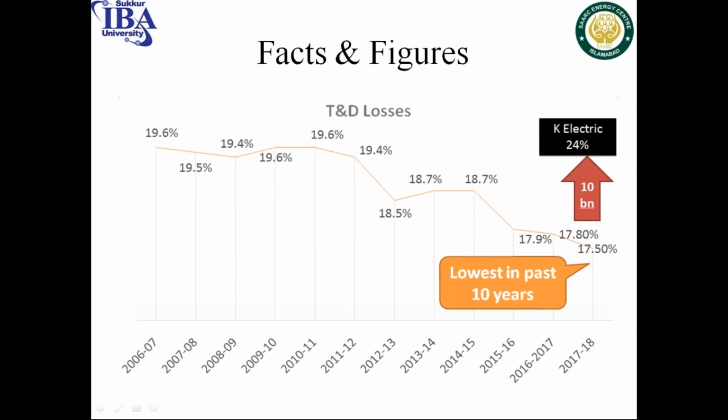So again, the capacitor banks cost money to implement, and how much cost are they actually causing when we implement them? So I have produced a table. I have formed a correlation between the capacitor banks installed and the amount of energy saved. I found that within 4 months we can save as much energy as accumulates to the cost of those capacitor banks being installed. Means in 4 months we can recover the cost of those capacitor banks.